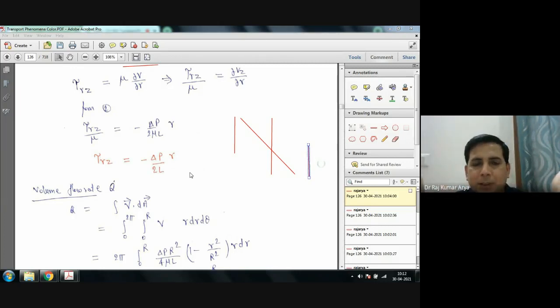The reason is that the fluid flowing always has a tendency to drag the pipe in the direction of the flow. So based on that, you can calculate how much force should be supplied by your clamps on the pipe in the opposite direction of the fluid so that your pipe remains as it is, right?